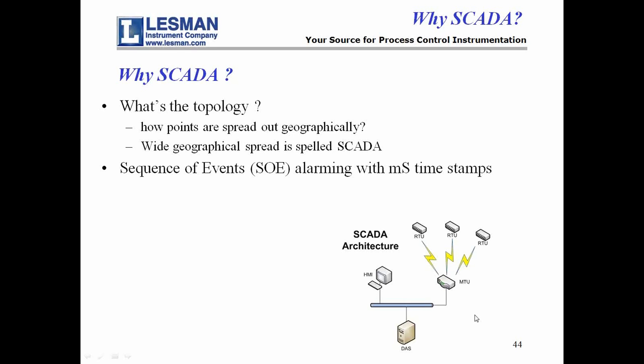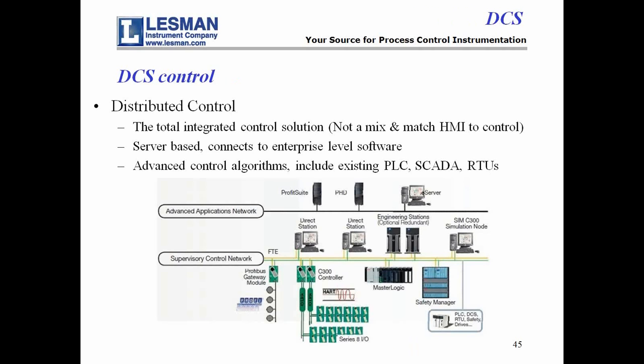It's server-based, and because it's server-based for everything, it easily connects to enterprise-level software, which is a big deal out there because the business people want to interact with all of this as well. And that's where some HMI software shines and other HMI software sometimes has holes in it. They do some really advanced control algorithms that just aren't out there for the PLCs or the PACs. What you also find in DCS control is you can have total ability to program your own control loops. You can do that with structured text or the other languages that they bring to the party.